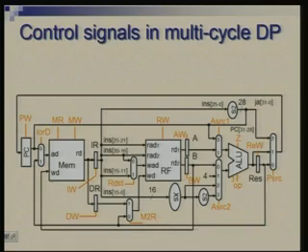But now things are handled a little differently, because PC plus 4 is sent to PC unconditionally in the first cycle. In the third cycle, the choice is either to transfer the new address or not to do anything. So, therefore, effect of Z will be brought into the way PW is being generated. In the first cycle we will have output of ALU directly through this multiplexer going into this.